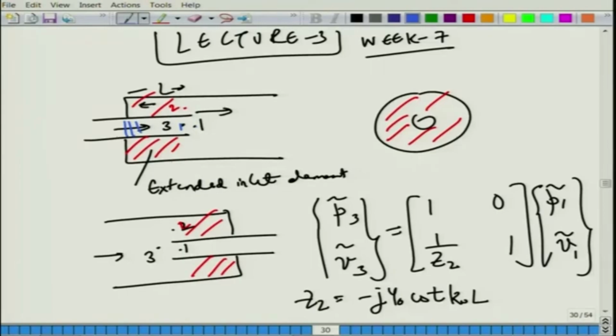It will definitely create some separation noise, but there will also be something like a head loss, a loss associated with the sudden expansion of the flow. That is probably going to aid in greater attenuation, but the main worrisome feature is the noise due to the free shear layers formed after the collapse of the potential core. That really is the culprit, and from experimental observation you never actually allow the flow to separate like this.